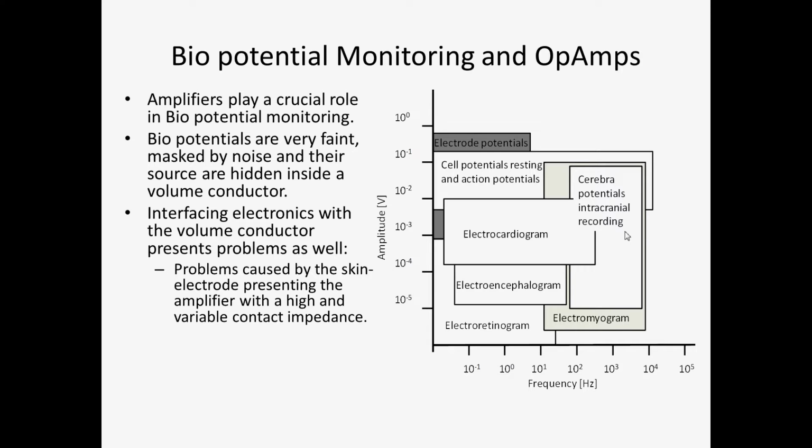They need to have ultra high input impedance because they need to withstand all this kind of possible issues arising from contact impedance imbalance between a number of electrodes. They need to withstand touch. I know this sounds weird, but the higher the gain of an amplifier is, the more it could be damaged by large inputs.